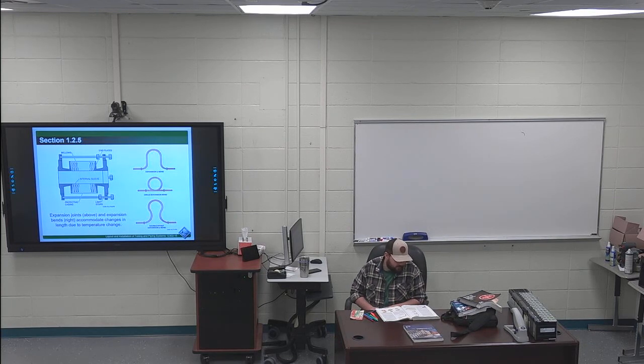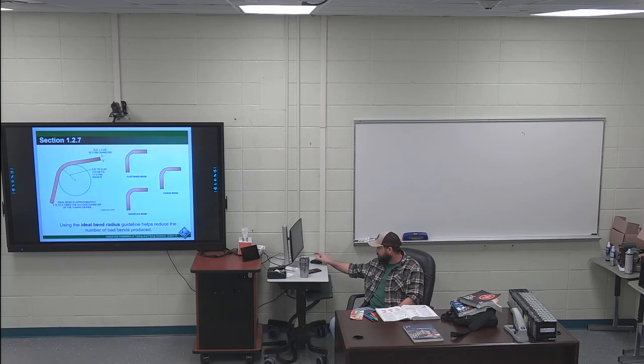We've talked about that. Page 10, bends and connections. So this is important. You have to have different radiuses for your bends and your connections. This is like a 5.5 inch radius in this bend. They talk about the different bad bends. So this is flattened. This is not used in the right die, more than likely, or kink. This looks like it was tried to be bent and then rebent, and then wrinkled bend. Again, wrong die is usually what causes wrinkled bends.